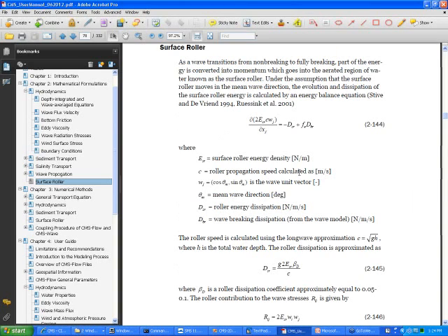And like I mentioned, it runs on the CMS wave grid. It's also a steady-state model, as you can see, and it runs every time the CMS wave model runs. It runs right after that, before CMS flow starts. And I'll go into the steering procedure in a second. So by steering, I mean how the CMS flow and CMS wave are coupled.